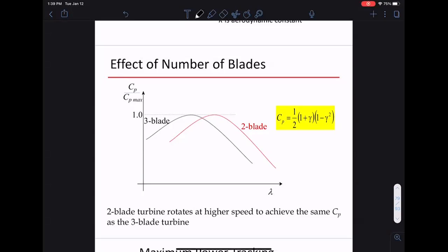So what happens if this thing rotates? It sort of wobbles back and forth like this, because the stress is not uniform depending on which position your blade lies in. It wobbles back and forth as it turns. So you have this wobbling motion. If you have something that's say 50 or 100 meters long, you really don't want this kind of wobbling to happen. Mechanically, it's very bad for the system.